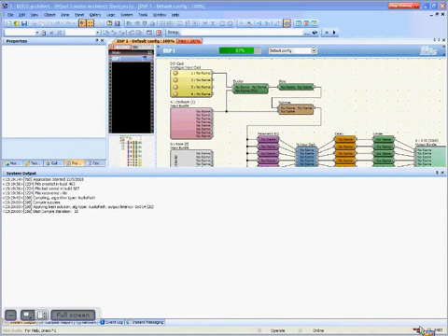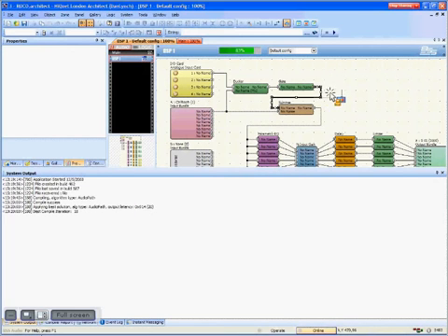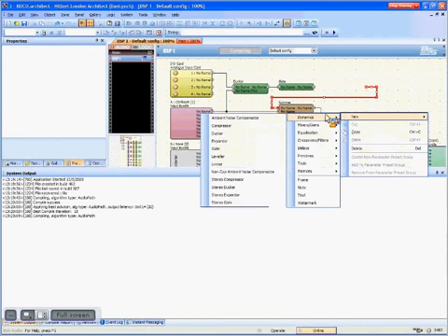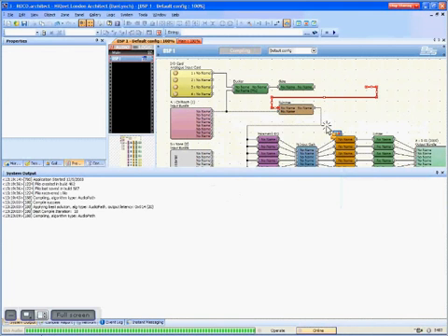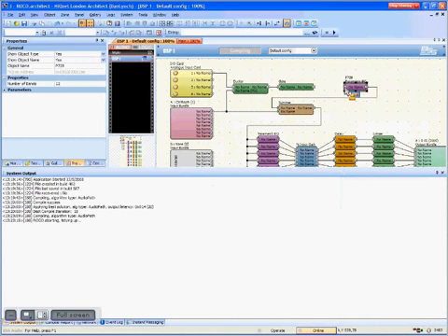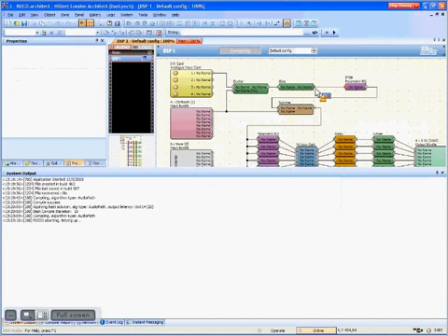Look right down here. See these 2 red and 2 green icons down here? Those will turn gray and kind of flash around in a circle anytime the compiler is running. You also see it listed over here. So if I go up here and I grab the wire, and I disconnect it from the gate, the compiler starts back up again. It starts to recompile. But before it has time to do that, let's go in here and I'll grab an EQ, parametric. Stick a parametric in there. What's going to happen? It's going to abort the compilation and just start over.